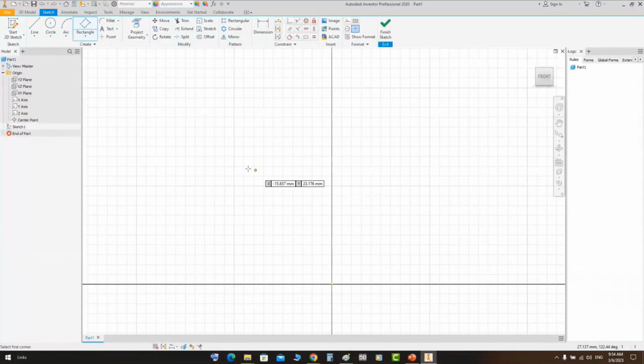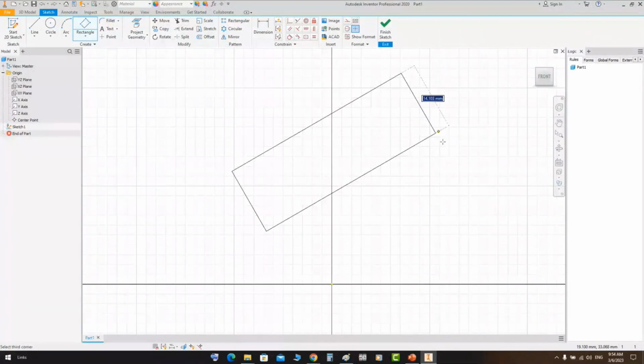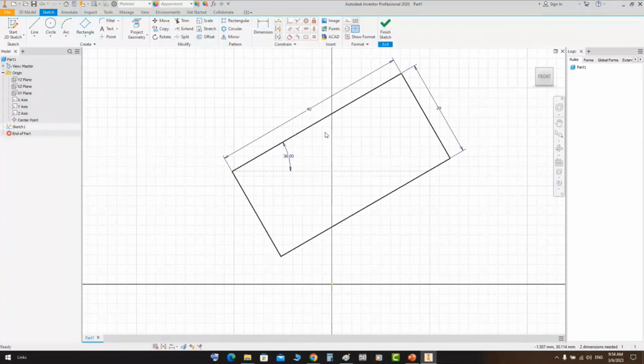So if you select it, you will be able to define the orientation angle. As mentioned, you can define the lengths during importing data, and the angle like that. After modifying this, you can insert the width that way. So you have this rectangle with the long edge 40 millimeters, the short edge 20 millimeters, and it's rotated by 30 degrees. Okay.